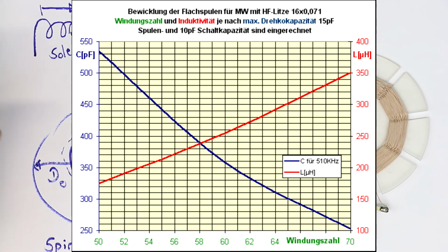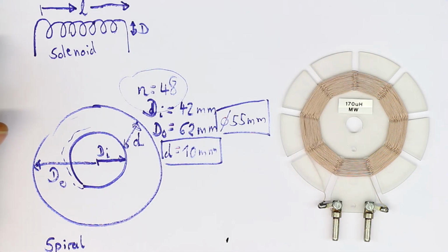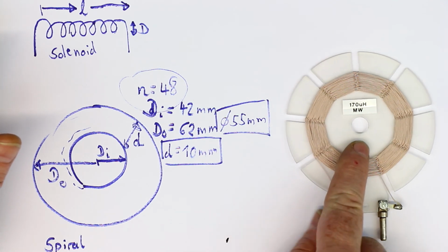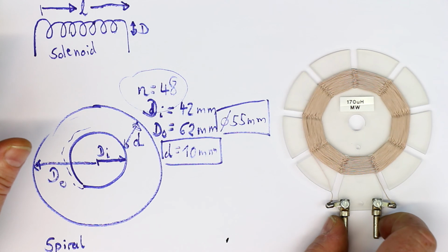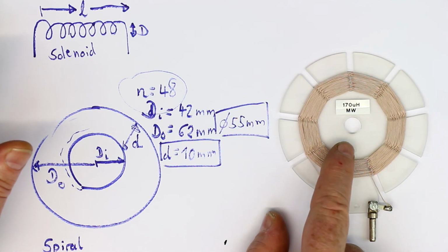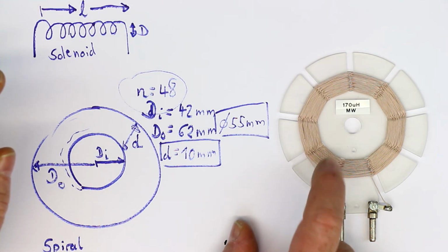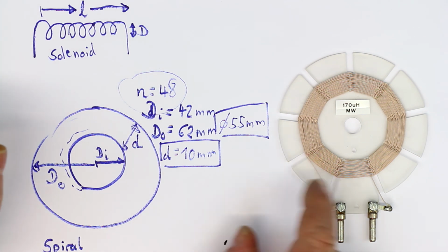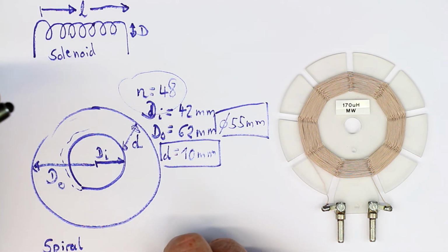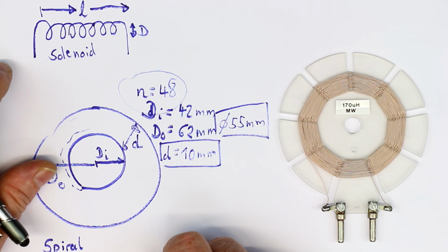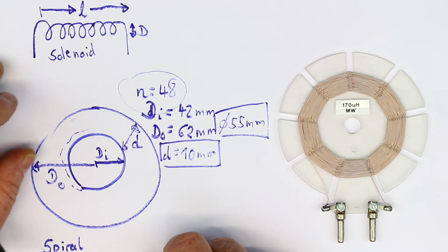So as you can see, we've again reached the limit of what we can really do with our spreadsheet. But anyway, we got the result that although spiral wound coils in theory give a very good Q factor with the right Litz wire, the internal proximity effect in the Litz wire ruins our Q factor, or at least makes it much worse than if we only took into account the skin effect and the external proximity effect.